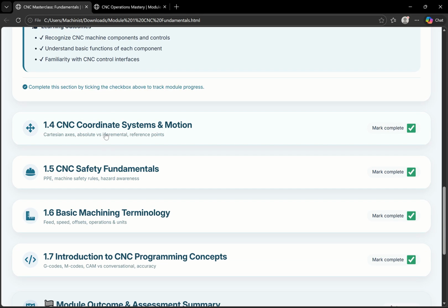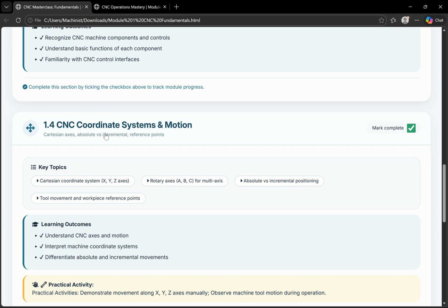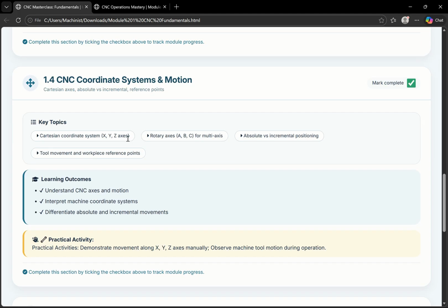We went ahead to look at the coordinate systems, like machine coordinate system, workpiece coordinate system, relative coordinate system, absolute measurement and incremental measurement, and referencing of the magazine or the turret, depending on the machine you have. Our machines have an absolute measuring system, so we don't reference the axes, only the magazine. Also, we looked at how we move axes X, Y, Z, A, B, C, and other axes, depending on which machine you have.